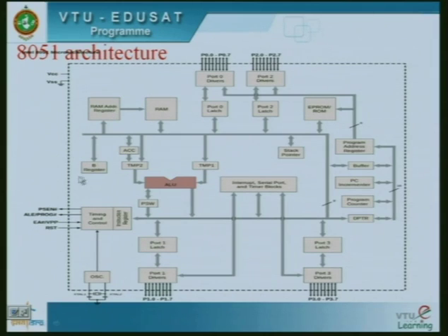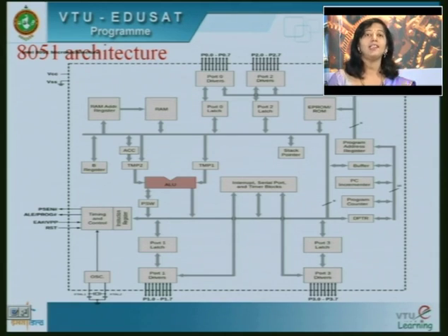Then this is the B register. Registers are nothing but a collection of flip-flops which will help us to store some bits of data. So if I have an 8-bit register, it contains 8 flip-flops to store an 8-bit value. So I can store an 8-bit number at once on an 8-bit register. An 8-bit register will have 8 flip-flops connected parallelly, or let's say serially, it could be either way.